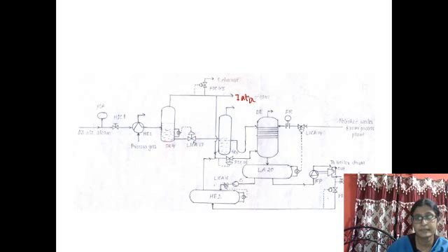In this way, analyze the design aspects of all 6 control loops, considering pneumatic type controllers and pneumatic type valves. Nowadays all are electronic type controllers, but the valve may be of pneumatic type, so air failure to open or air failure to close type should be chosen for operation.